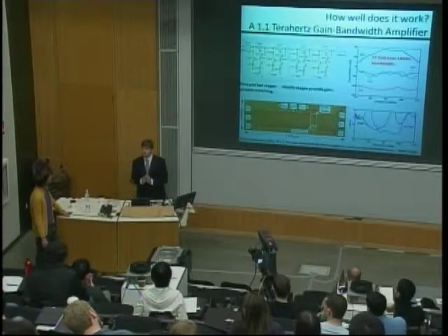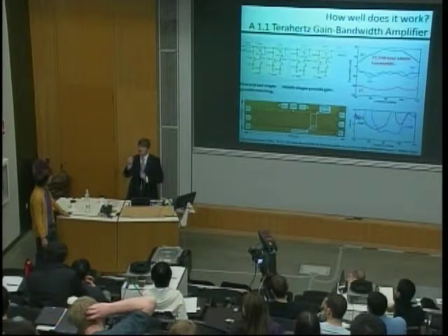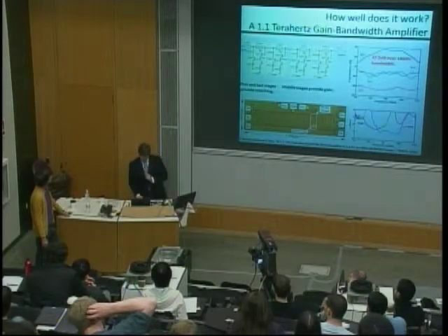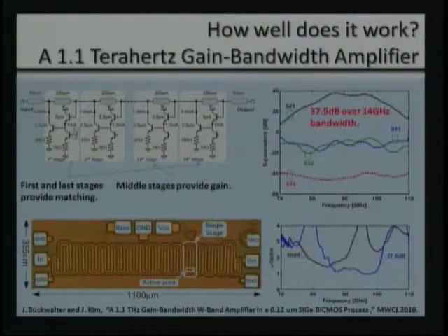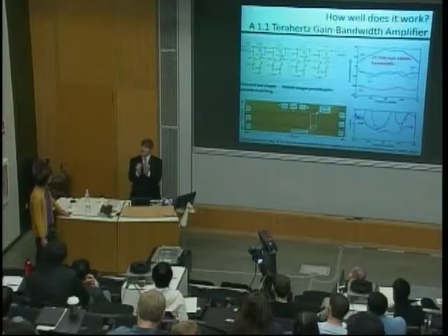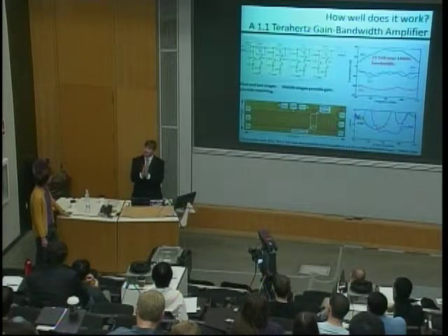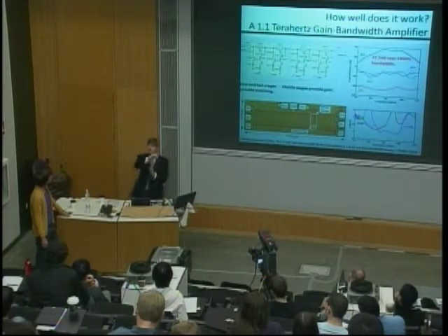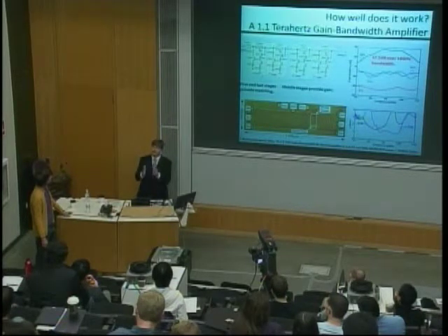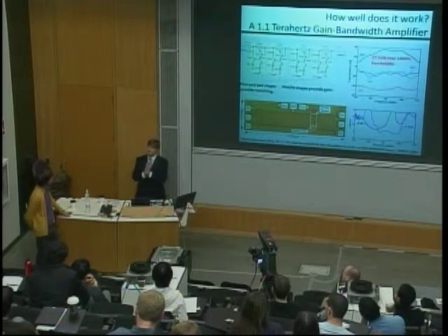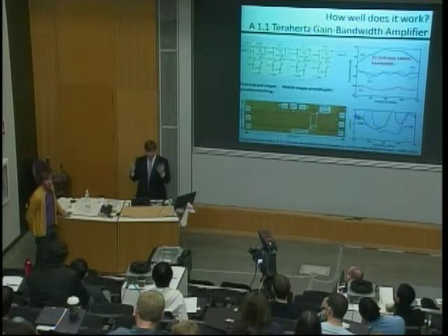The net feedback is positive, correct? The net feedback is positive across the transmission line. I'm just talking about the active part of the circuit, the emitter follower and the common emitter. That has negative feedback. So for the actives themselves you can introduce negative feedback, but the net effect through the transmission line is positive feedback, exactly. But you're right. There's some more work to do in really showing a lot of sample sets and showing that the PVTs are actually really good over all corners.